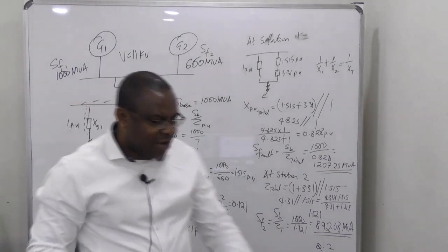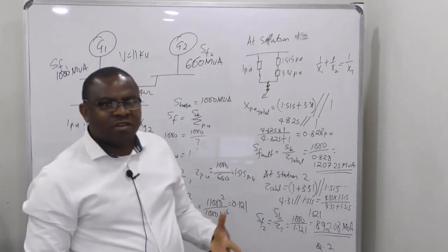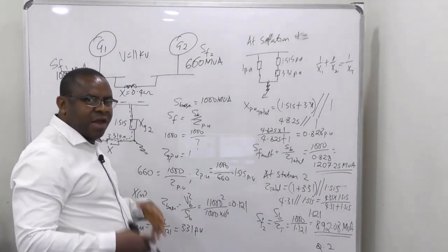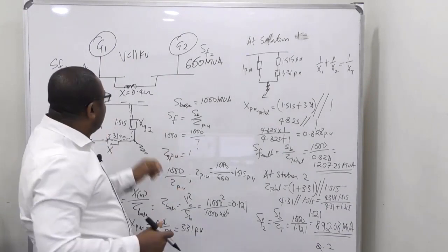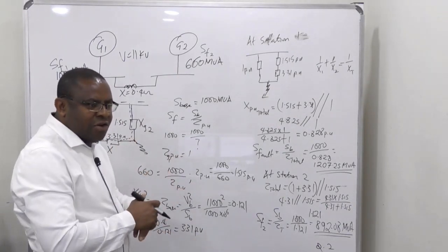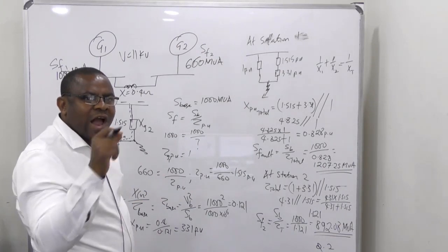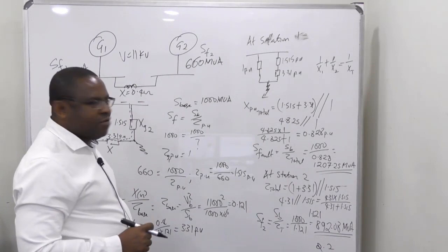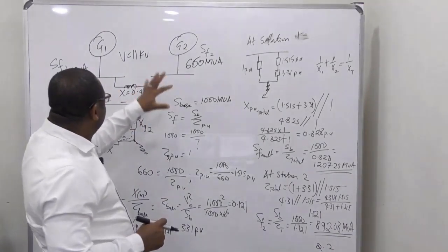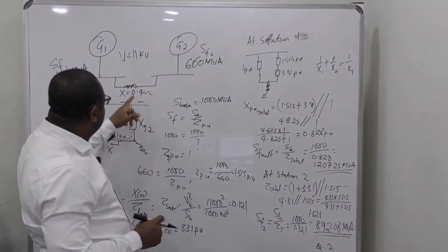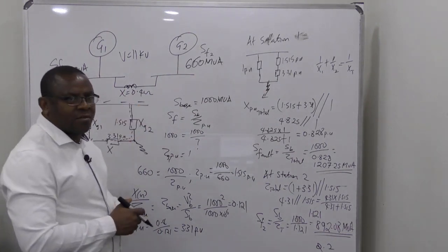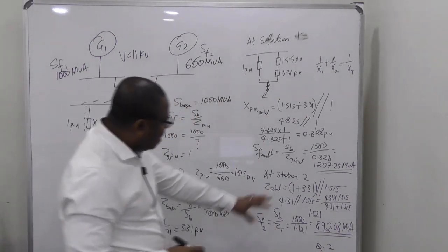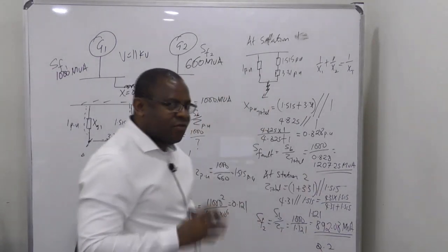Because sometimes, people will just say, "Look, let's parallel this together." Another person will say, "No, if you parallel together, there will be an increase in fault level," which is true. Now they just put a reactor to limit the fault level, and they did not calculate the exact size of a reactor that we use to limit that fault level. Because for you to limit this fault level to be very small, you need to increase this size. Remember that what we have calculated here, you can convert them to kA, but these are the two answers that they want, and that is 14 marks.